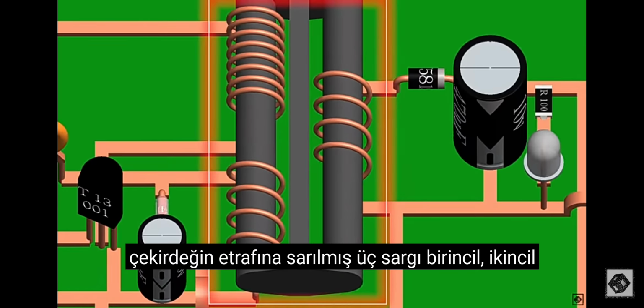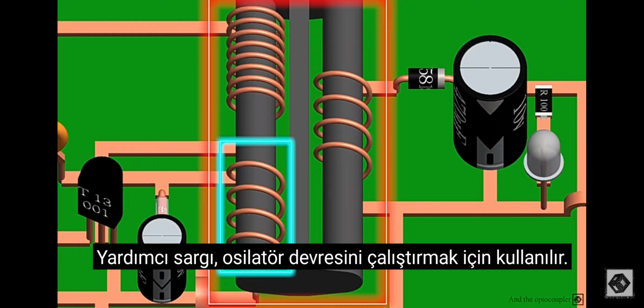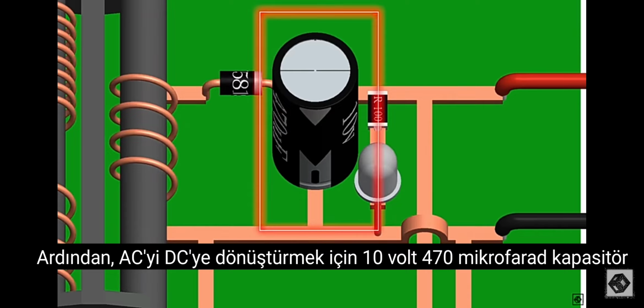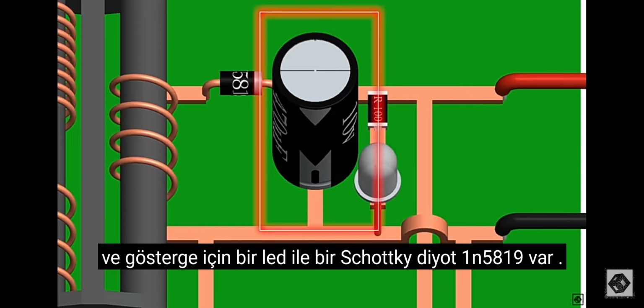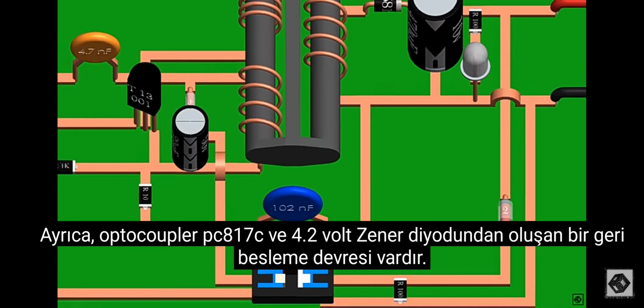This is the transformer. It has 3 windings, primary, secondary and auxiliary winding, wrapped around the core. It is used to step down the voltage. The auxiliary winding is used to run the oscillator circuit. Then we have a Schottky diode 1N5819 with a capacitor of 10 volts 470 microfarad to convert AC to DC. And an LED for indication. Also, there is a feedback circuit that consists of an optocoupler PC817C and a 4.2 volt Zener diode.